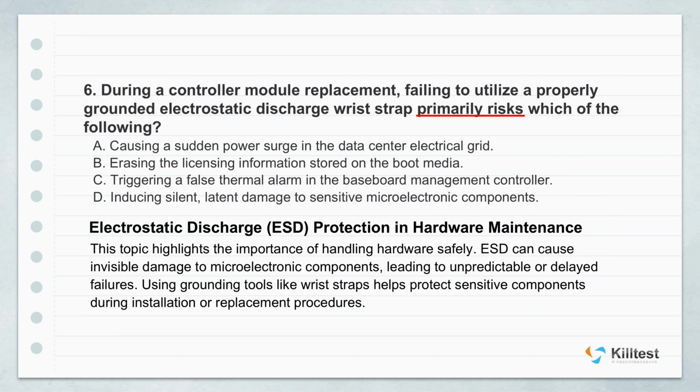Electrostatic discharge, or ESD, induces silent latent damage to sensitive microelectronic components. I want to focus on that word latent, meaning it doesn't break right away. That is precisely what makes ESD the most terrifying threat to a hardware engineer. You might shuffle your feet on the floor, build up a static charge, and then touch a memory module without wearing a grounding strap. You won't even feel the spark. You plug the module in, the system boots up perfectly, and you think you're fine.